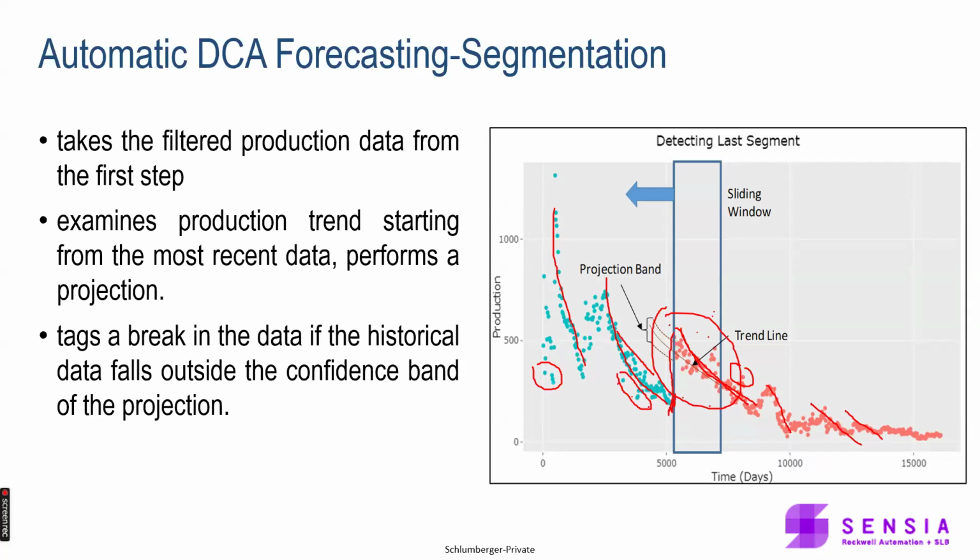It can take the bubble point pressure as a threshold, right? So it will take all reservoir and facility constraints and apply them to your forecasting with a multi-forecast. It will do oil at the same time in the background. It will do water cut, gas oil ratio, and pressure forecasting, and then combine those to give you when the well will die or when the well will stop.